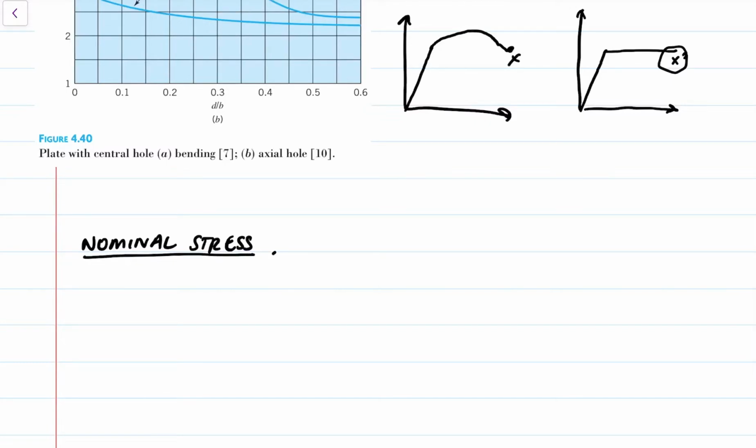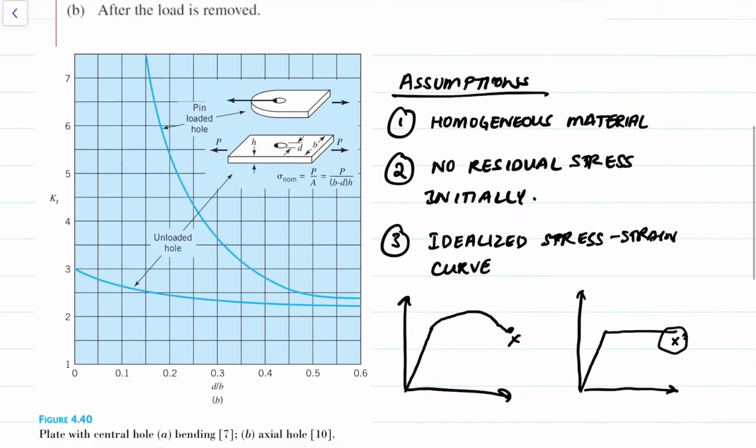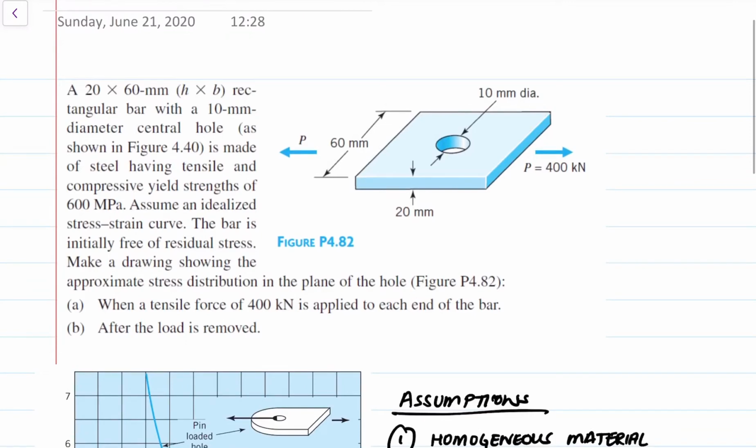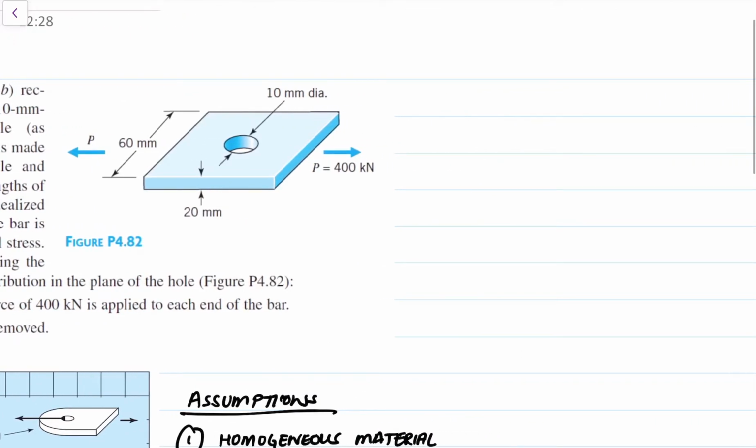And one thing I forgot to mention in the previous video, or rather I didn't mention very explicitly, is when you're picking the point on the part, or in this case the bar, where you are evaluating the nominal stress, you want to ensure that you evaluate the nominal stress at a point where the area where you have material is minimum. So what this means is, in this case, I would take this section right here, right? Because the total area at that section is going to be less than anywhere else on the part. But that's not always necessarily true.